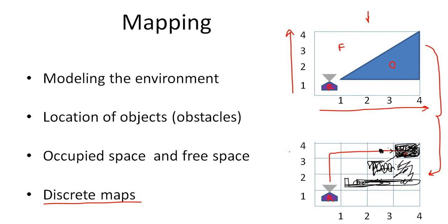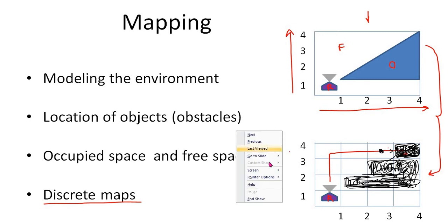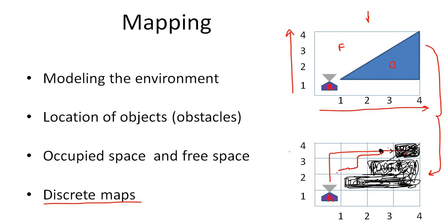But for that, the robot has to move a little bit more in every direction, every orientation, and then it can detect all the obstacles in the room. You can see the lower obstacles are not visible from the current location of the robot. So to detect the lower obstacles, the robot will move back from here, and from these cells it can detect the lower obstacles.